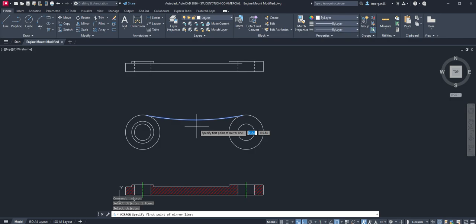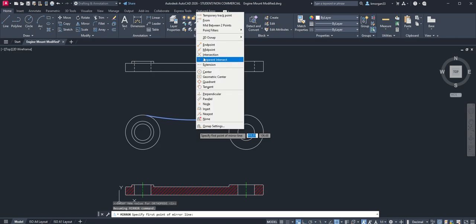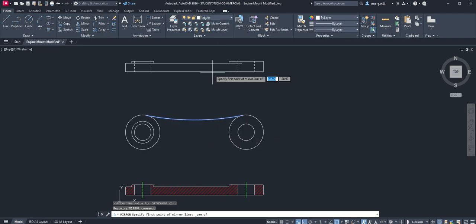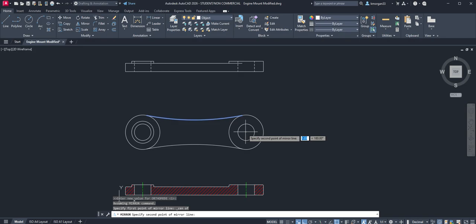What we need to do is turn on the center point. So go ahead and do your shift right click, and then turn on your center. Center is right here. The center point is not grabbable, so we will find the center on the right side. Here is the center, and click on it. If you click on it, we will mirror with this center axis, so you have a symmetry from here to there, and from there to here. Of course, finish it.